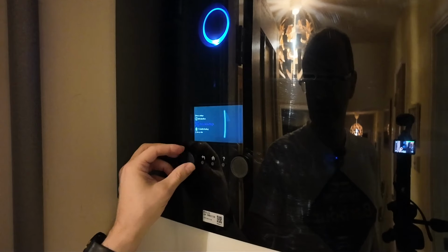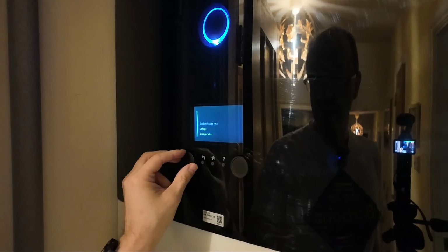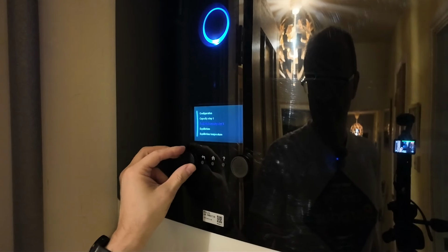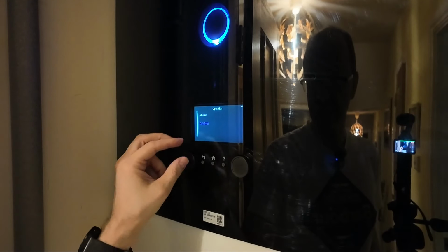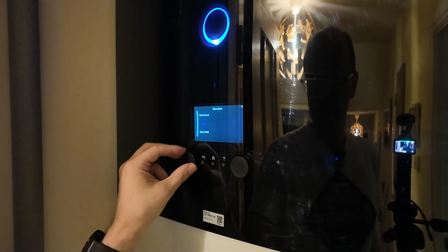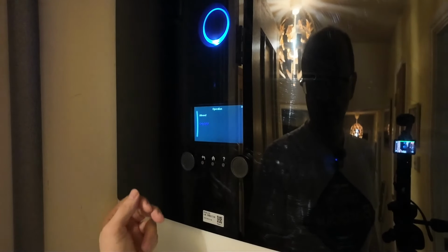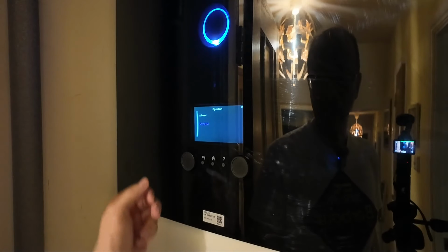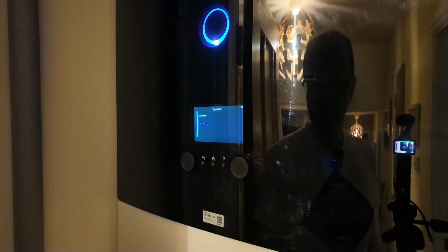So I went back into installer settings. I went to the backup heater. You remember last time that I set it to an operation mode of being restricted. This one up here. I've now changed it so that it's allowed to come on only for domestic hot water. I then reset the disinfection time for midnight on Sunday, and woohoo, the disinfection worked this time.